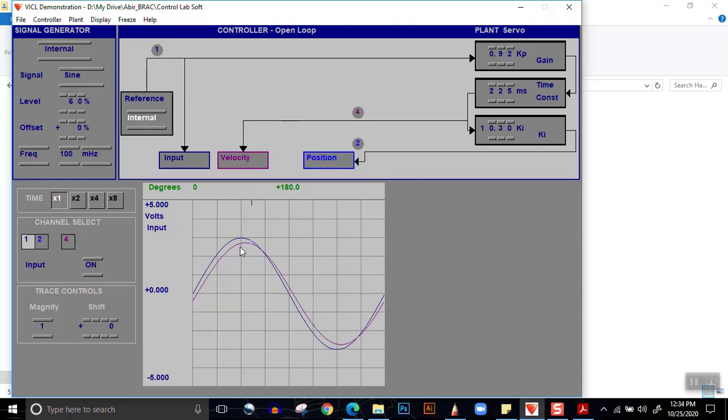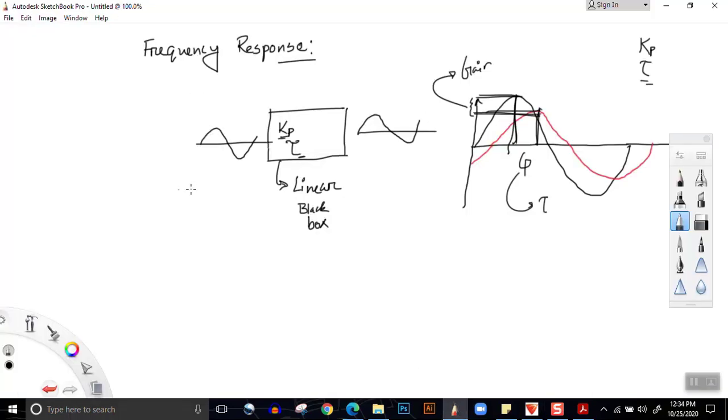One thing to be noted is that the difference between step response and sinusoid response is that in sinusoid response, you gradually increase the voltage, it reaches a peak and then gradually decreases. As a result, you will see a smooth transition in the speed of the servo motor itself.